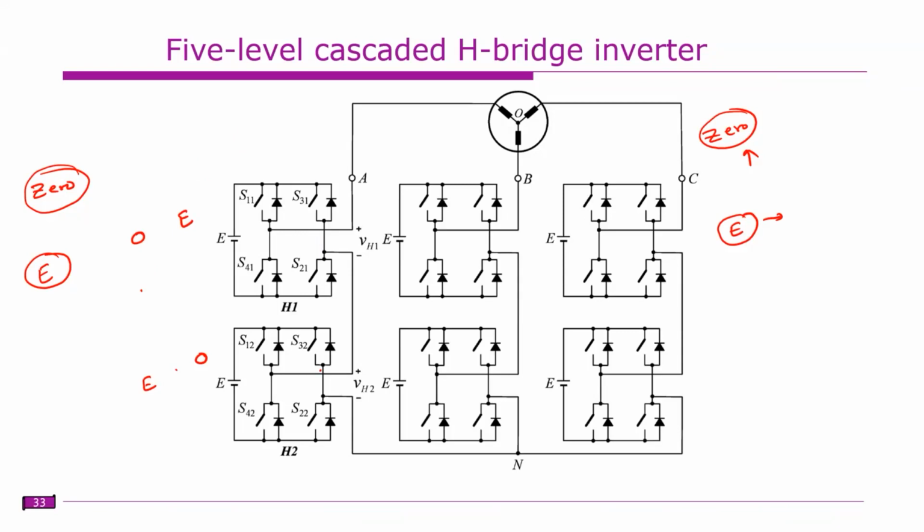So this is particularly required when it is connected to batteries or capacitors. If capacitors are connected, in this case one capacitor will be discharged more, which means the voltage across this particular capacitor will be reduced when compared to the other one.